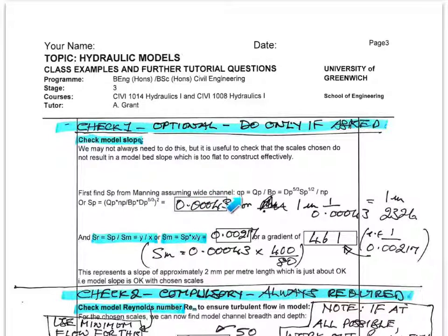So Manning's for a wide channel, expressed in terms of the flow per meter width, little q, subscript p means prototype: little q equals 1 upon n p, that's n in the full scale, times the depth to the 5/3 times the slope to the half. Deliberately avoiding the use of y here, the depth in the prototype would be approximately equal to r if it were a wide channel. So d to the 5/3 s to the half over n, from which we work out s here,